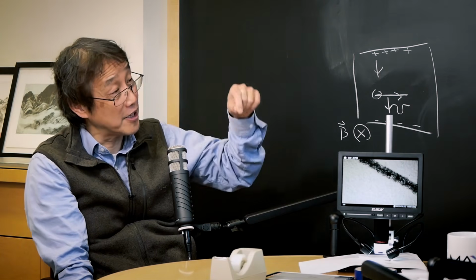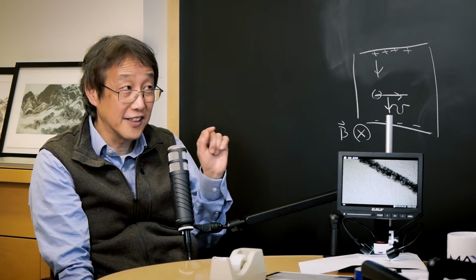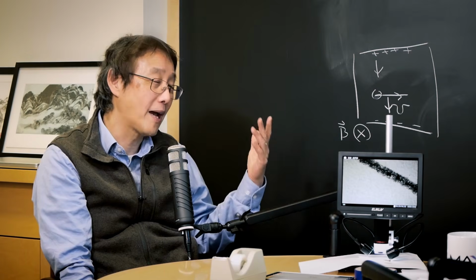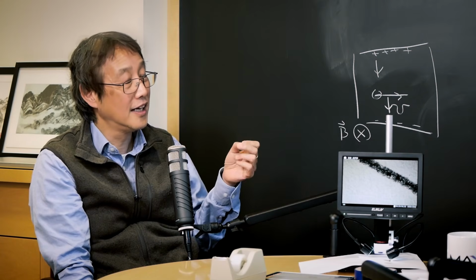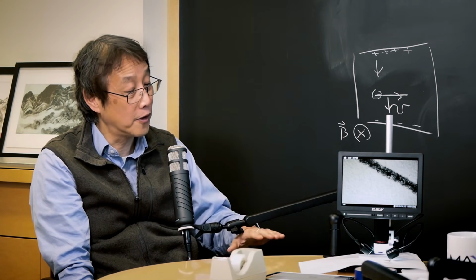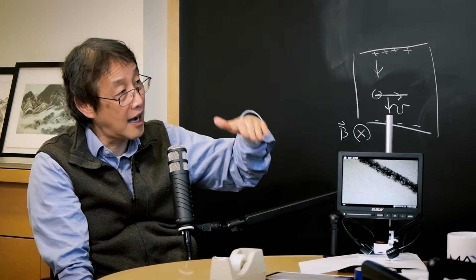That's an extremely difficult experiment, like modifying your own AFM to make these tips. It sounds pretty tough. It's tough, but it was doable. How do you measure the thickness? Okay, that's another part. You're using an AFM again, another AFM that measures the thicknesses, and that's yet another thing later. Back then we just didn't notice, but I think that can potentially have problems, because the Van der Waals force on top of silicon oxide and on top of the graphite can be different, and so it pushes the tip.